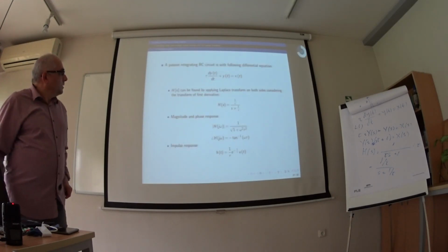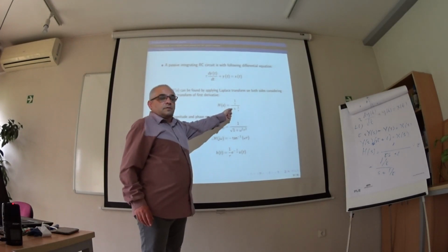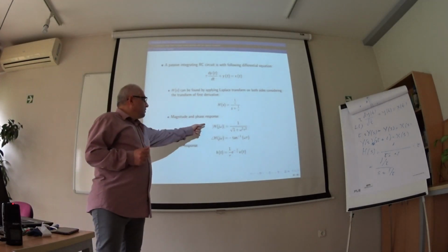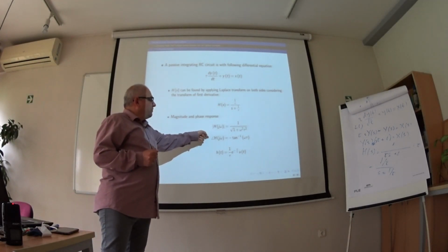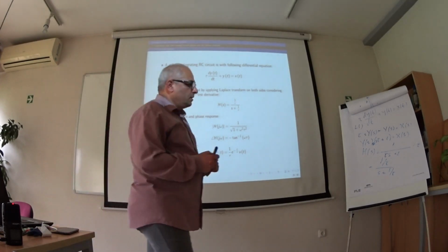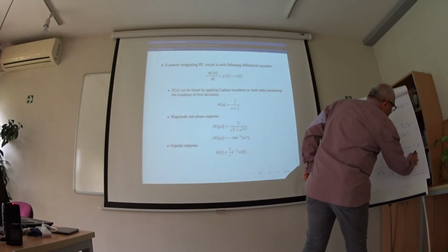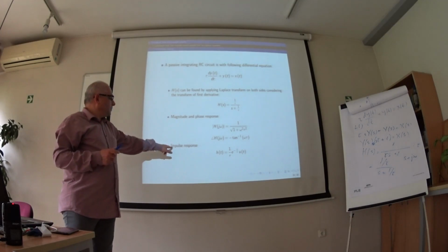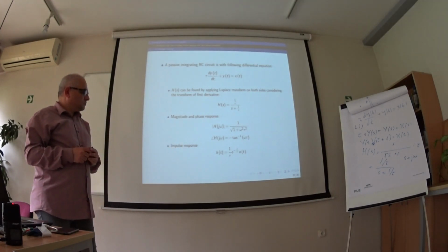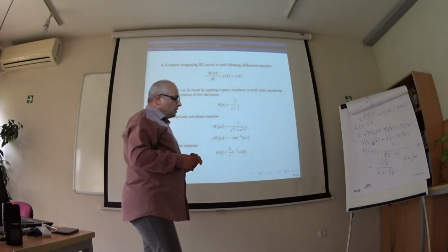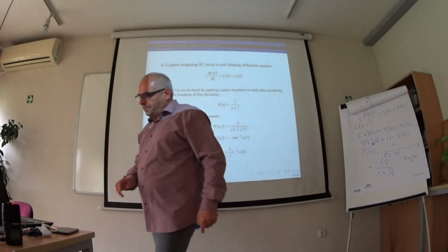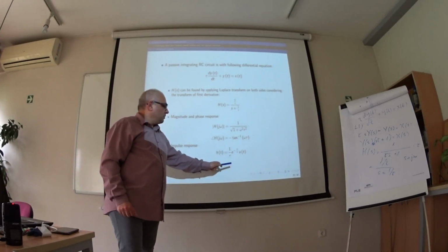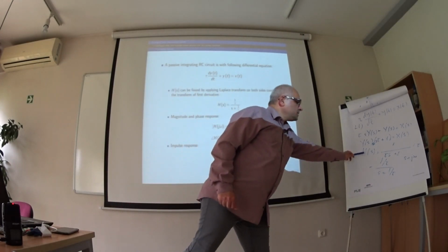So here is our transfer function. We just found it, and magnitude and phase response. We can find them very easily by substituting s with j omega. Impulse response, and this impulse response is just by application of inverse Laplace transform over the H of s.